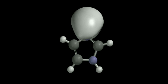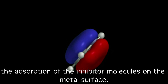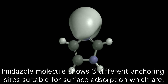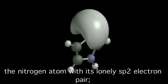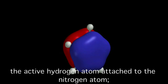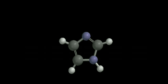The inhibition of carbon steel corrosion by imidazole compound is due to the adsorption of the inhibitor molecules on the metal surface. Imidazole molecule shows 3 different anchoring sites suitable for surface adsorption, which are the nitrogen atom with its lone sp2 electron pair, the active hydrogen atom attached to the nitrogen atom, and the pi bond of the aromatic ring.